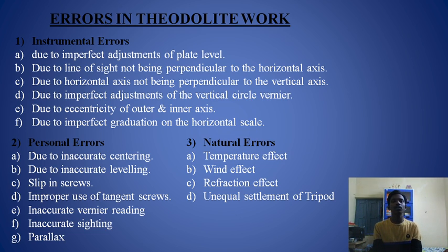And the second one is due to inaccurate leveling. Sometimes we forget or omit doing the leveling part. We have to level the instrument with reference to the plate level and altitude level. But if we omit the leveling of the instrument, then that will be a personal error.